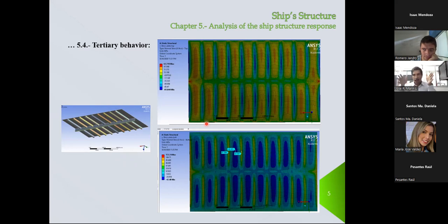If you consider a completely clamped plate, the stresses on the side are more or less double the stress at the central part. You have a certain value, positive or negative, and in the center you have the opposite sign with about half of that. Then you go back to the other side and recover the same value as before. You see something like that here, but the relationship of the values is not twice.